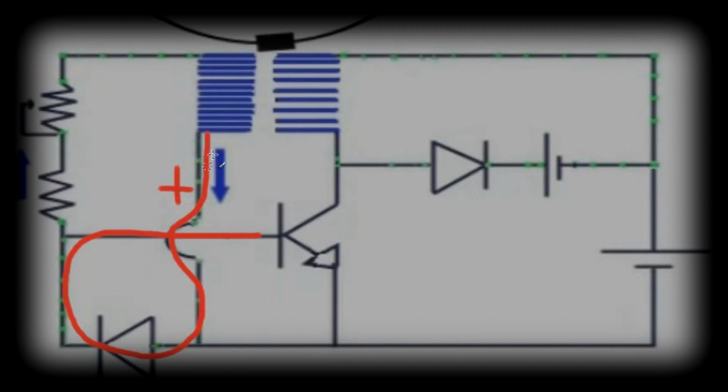And that's how this trigger coil is biasing through the diode in its circuit. Sending plus through here, making sure it stays on this side. Create a solid DC pulse on the base here, 5 volts or whatever. Probably reaches a solid 5 volts after saturating.